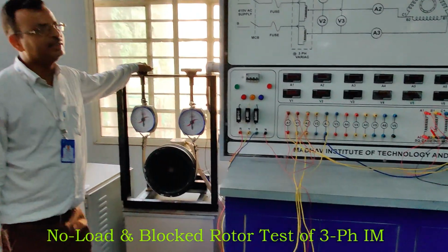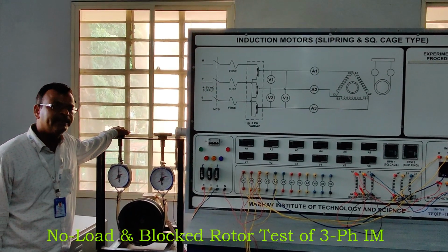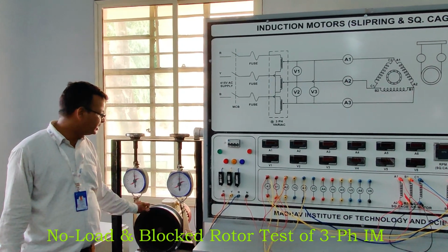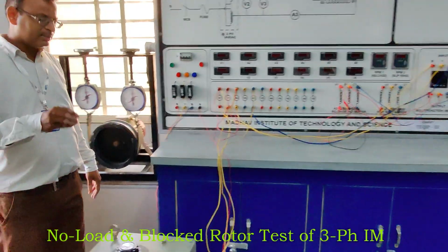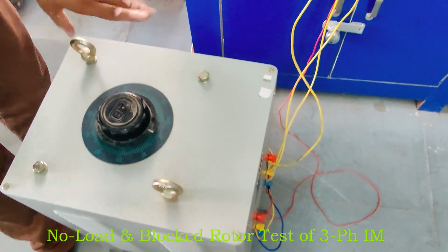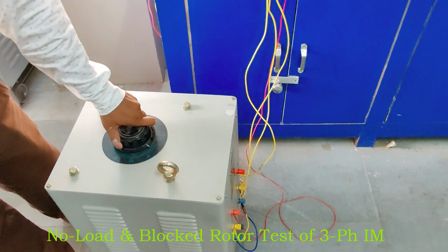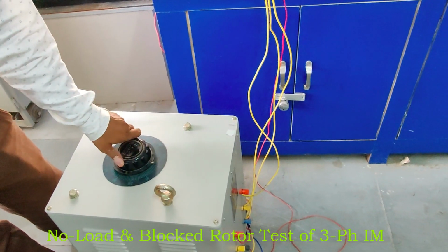As we already studied in the theory part of this experiment, this test is performed at rated voltage. The rated voltage of this machine is 415 volts, and the rated speed is 1500 RPM. With the help of the auto transformer, you gradually increase the voltage. The main precaution in any experiment is that the auto transformer should be kept at zero position.